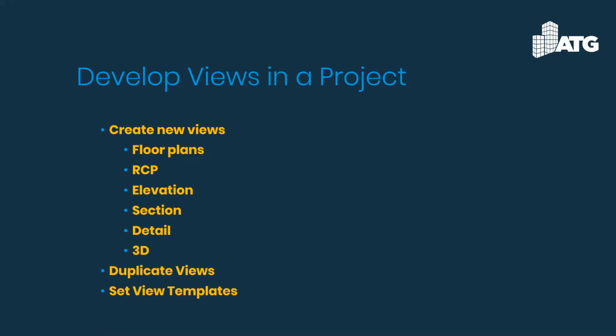You also have what are called dependent type views. Dependent views don't necessarily create a copy of it, but what it does is it allows you to go in and start using match lines. And this is going to be typically for your larger square footage type buildings, where if you try to put the entire floor plan on, let's say, a D size or an E size sheet, it still doesn't fit on there. It's just way too large.